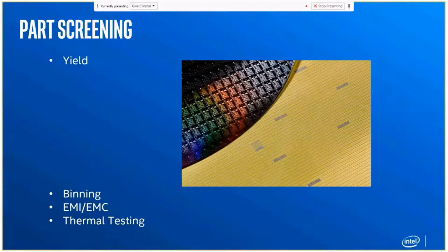These will be simple tests done not by major software engineers, but by production technicians, right? So it's really simplified. You have a traffic generator that pumps in a lot of traffic and then it comes back. Then you start heating the device up to the temperature that it's certified to work at. Why are we doing that?